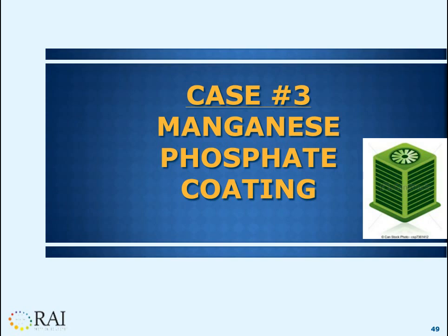Manganese phosphate is a crystalline coating. It's called a pretreatment because it's so thin. And this crystalline coating absorbs lubricating oil and holds it during the break-in period. Manganese phosphate coating itself has lubrication properties, so it and the oil provide temporary break-in lubrication.